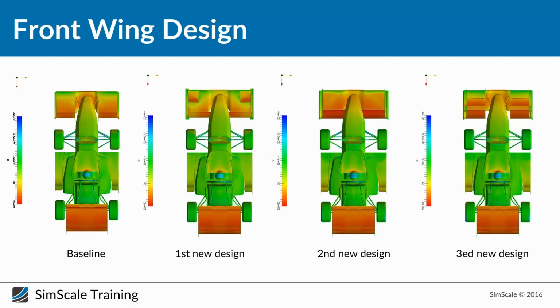So maybe later, or the next step, when you take your design for a new front wing, you can take this point into consideration: that the cascade elements will really reduce the performance of the front wing in terms of generating downforce. Let's move to the next design, which is the second new design, where we have created a wing